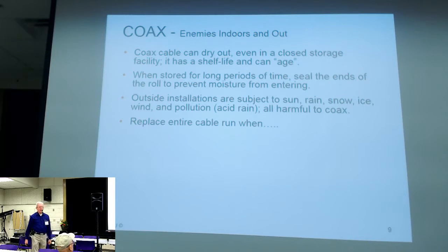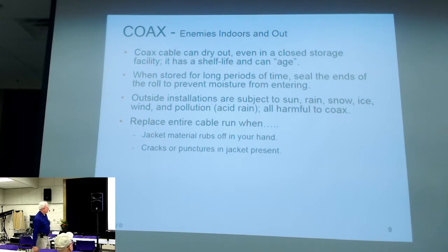Replace your coax. Now, this is important, guys. Replace your coax. If you go outside and you end up with black on your hand, that means that your jacket is starting to go. It's starting to be UV'd. Number 2, cracks or punctures. What I always like to do is inspect it very carefully and look for cracks or punctures. Number 3,